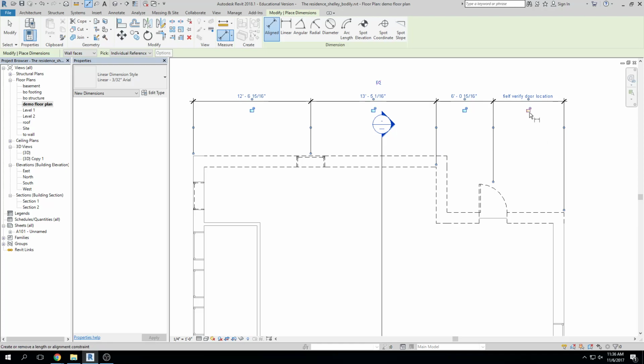You're also going to notice we have a little lock right here, okay? What this little lock does is that, with this dimension associated to these objects, if I click on lock, that means that if I move this object, or I try to, I've placed a constraint on it. So if I try and move it or do something to it that breaks this dimension, I'll get an error and it will say your constraints are not satisfied, something to that effect, okay? So I can constrain these if I don't want anything to move.